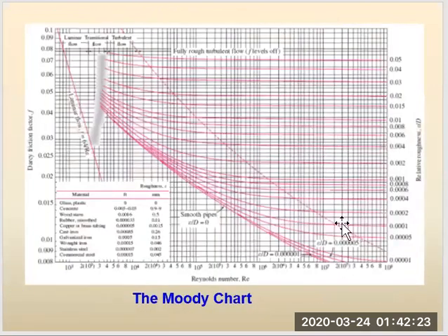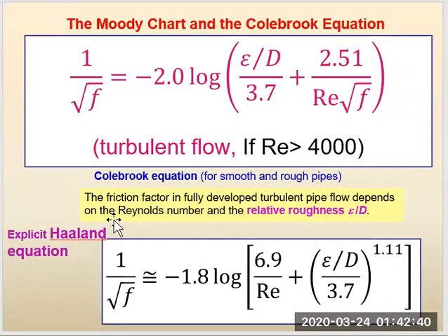This is a more detailed or actual form of the Moody diagram. So you can use the Moody diagram to calculate your friction factor for turbulent or laminar flow. But since you already have access to the formula and correlation, it is really easier to calculate. So just use these equations, or 64 over Reynolds number if you have laminar flow.